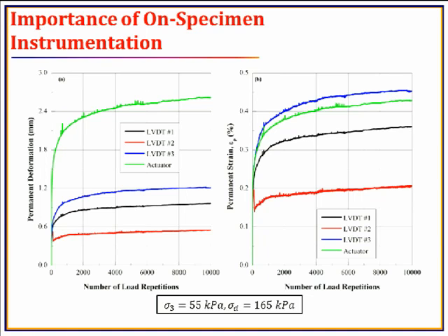On the other hand, the 3 LVDTs that we have are moving with the specimen and along 3 directions. So instead of just depending on the top of the specimen, when you have 3 different radial LVDTs sticking up to the sides of the specimen and moving along with the specimen, you can better capture the permanent deformation trends or the permanent strain trend that you are seeing here.